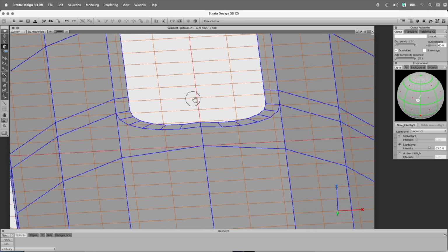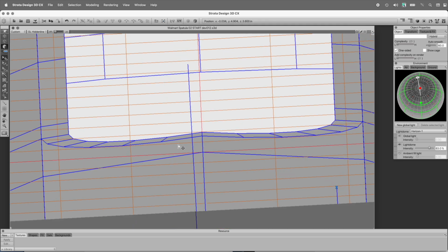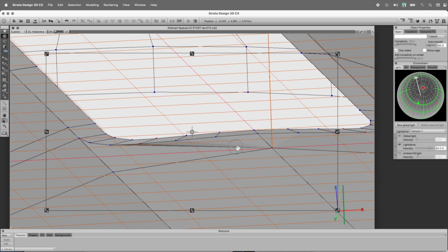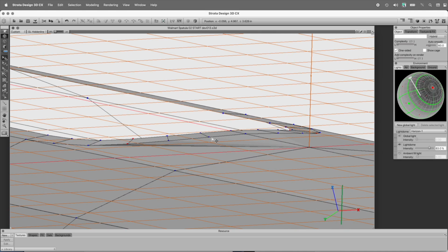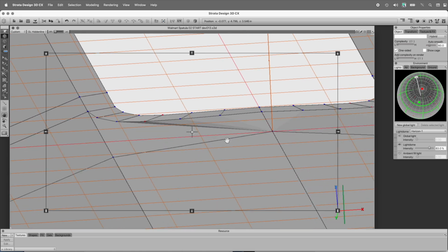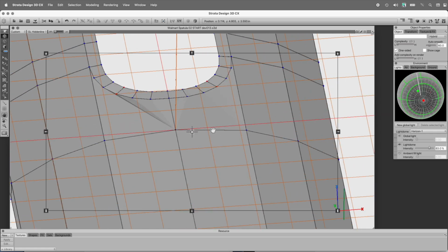to move up and manually give curvature to this area here. Now I can manually select these points and I can move them and contour the curvature that I want, like this. Just grab these. And so I can blend that curvature down until it blends. You can see I've just created that blend down into this surface here. Okay, so now we're ready to patch this together.